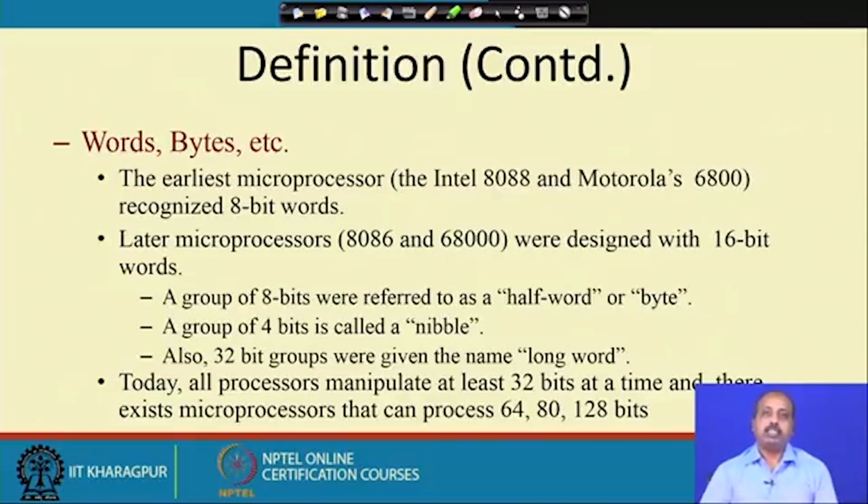Now, when the 8086 was introduced into the market, you could not just take out the 8085 chip and put the 8086 chip there, because the data bus size itself changed from 8-bit to 16-bit. So the hardware becomes incompatible. After understanding this, Intel went one step back and made the 8088 an 8-bit processor, though its internal operation is exactly similar to the 8086, but from the outside world it has an 8-bit word interface. So all the systems in which the 8085 was being used can be replaced by the 8088 processor, and the hardware remains unchanged. Of course, the software has to be changed, because that will now be for the 8088, but the hardware part does not need to change.